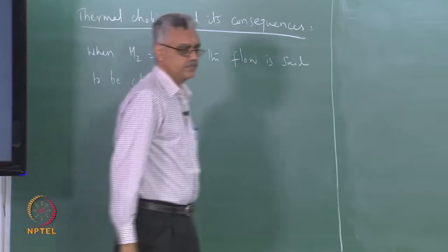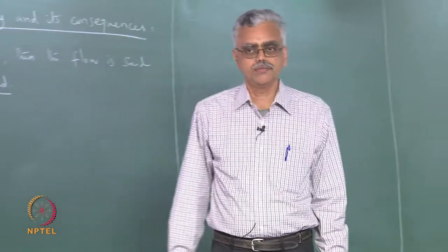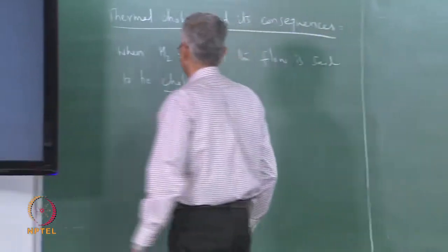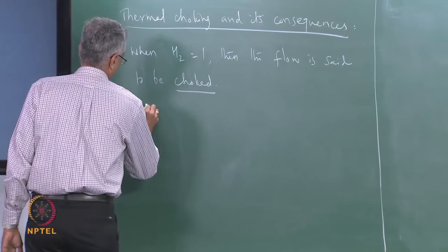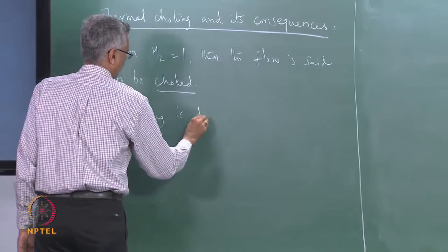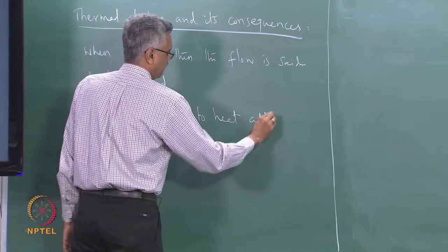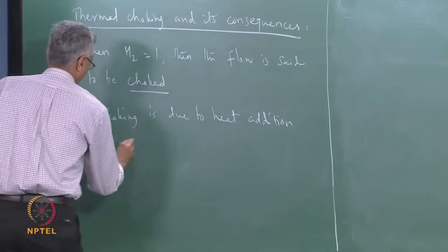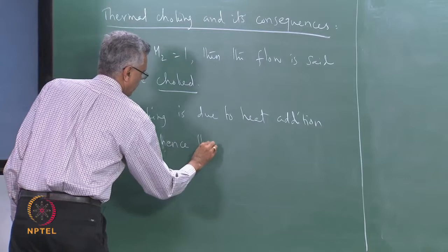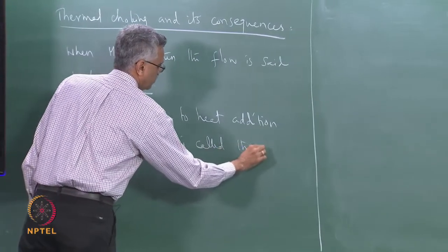Now, choking can be due to a variety of reasons. In this case choking is due to heat addition, and hence this type of choking is called thermal choking.